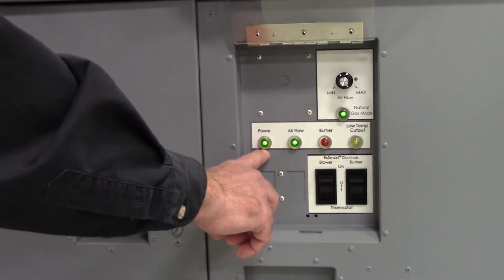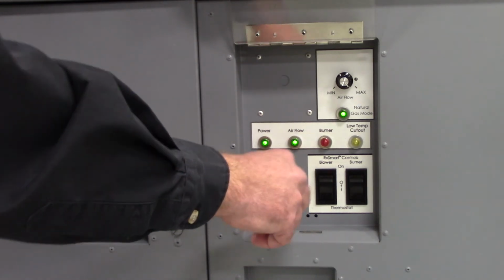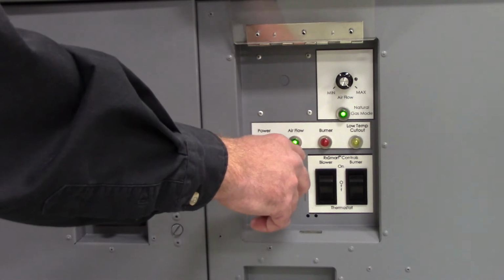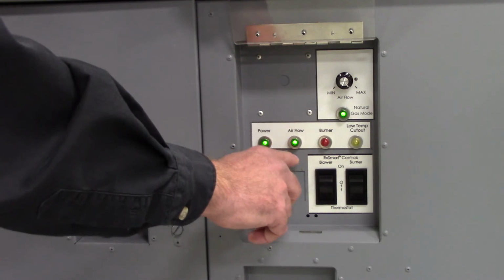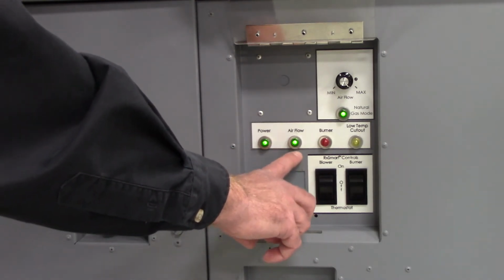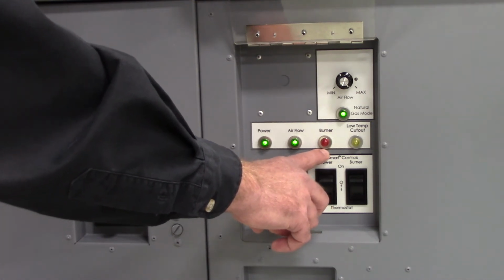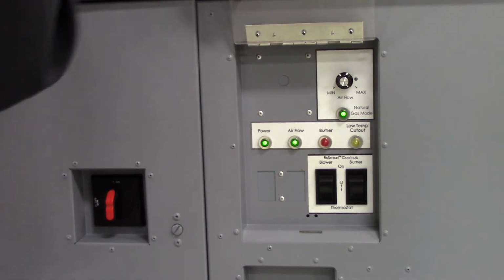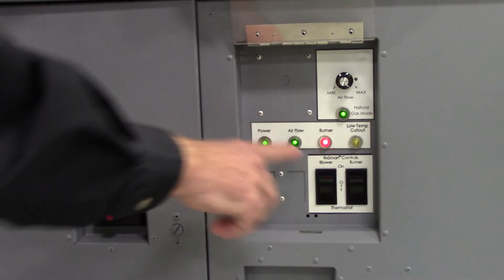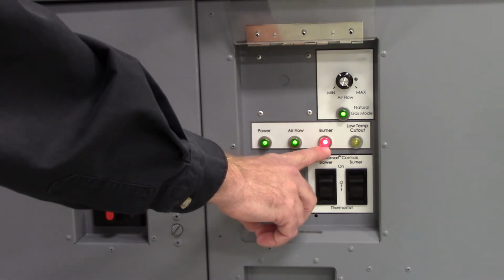Depending on what mode it is in, the airflow sensor will kick on once we turn the system in ventilation mode, comfort mode, or process heating mode. Once the fan starts to turn, it'll turn on the airflow switch. This is the burner ignition. So in comfort heating mode, get that to turn on. Comfort heating mode, and in process mode, when the burner is on, this red light will come on.